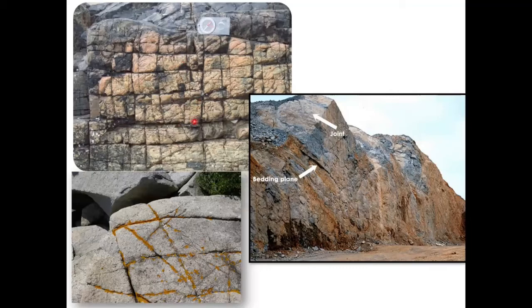And when you find something like this on the outcrop, first you have to measure strike and dip. Fractures are planes, so we measure strike and dip direction. So when you find an outcrop like this, the first thing to measure is the strike and dip angle of each fracture on the outcrop, and you need to make a note for each set. So this is one set in this direction.